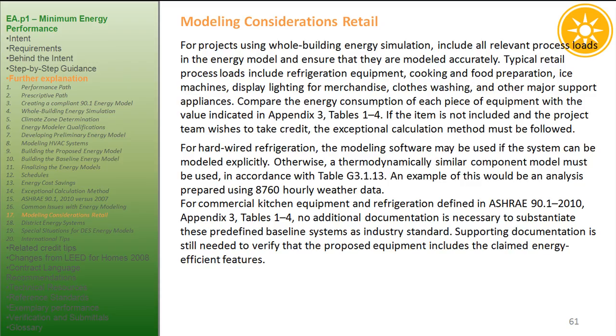Modeling considerations. Retail. For projects using whole building energy simulation, include all relevant process loads in the energy model and ensure that they are modeled accurately. Typical retail process loads include refrigeration equipment, cooking and food preparation, ice machines, display lighting for merchandise, clothes washing, and other major support appliances.